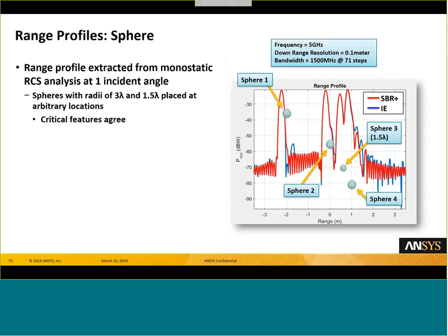So the vertical axis in this case is giving us the response of the backscattered power, and the horizontal axis shows the range to the object. So notice in the middle of the horizontal axis, we've got a range 0. That corresponds to the target range defined previously by that X-max value. So think of a negative value on that as features that are in front of that target range, and positive numbers correspond to features that are behind that target range.